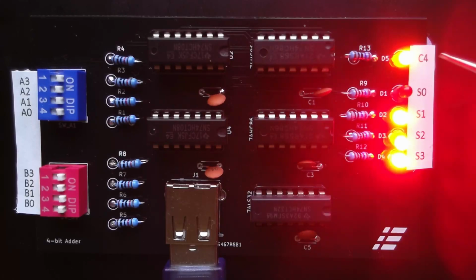So what we get should add up to 30 if we add in 16. So the carry out is actually representing the value 16 in this case, one more than the 15 that we can get to. So we have nothing on 1, but we have a 2, 4 and an 8. Well, 2 plus 4 plus 8 equals 14. So we have 14 plus 16, which is indeed 30. So we can see that it's working, but we have reached our limit. 30 is the biggest number we can represent with this circuit.